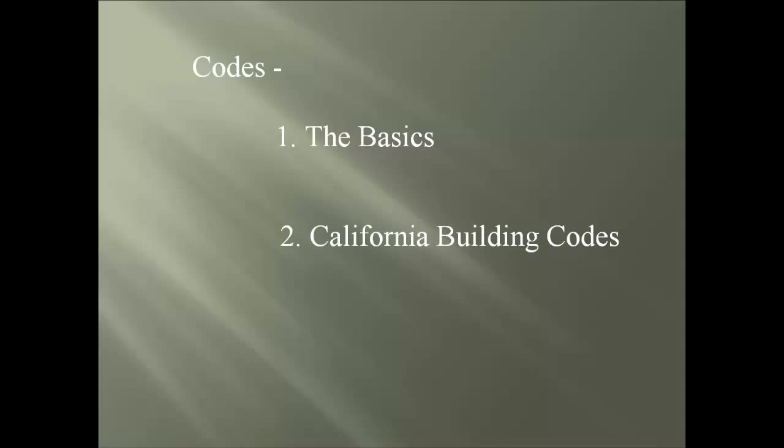Next, we enter into the California Building Codes, the CBCs, first looking at what makes up the entire set of CBCs, and then review key points of Chapter 17 and 22 for the QC and QA professionals. Then we take an interesting look at a document that is being used on projects that are governed by the federal government. The FEMA 353 is a critical specification for the QC and QA professionals.